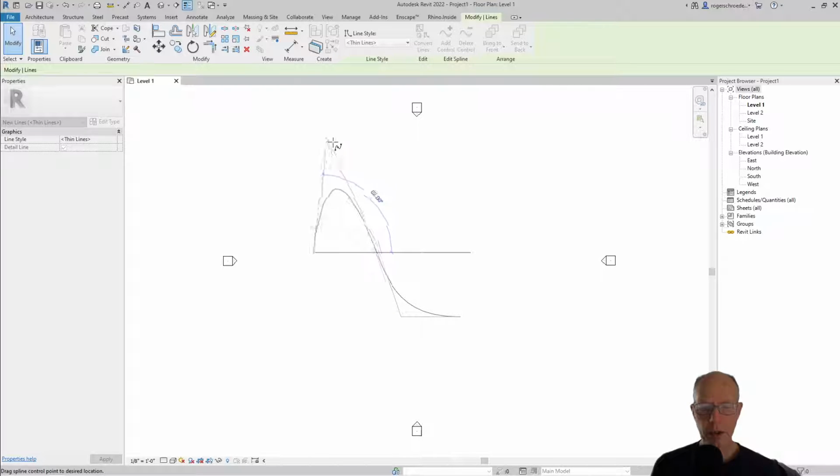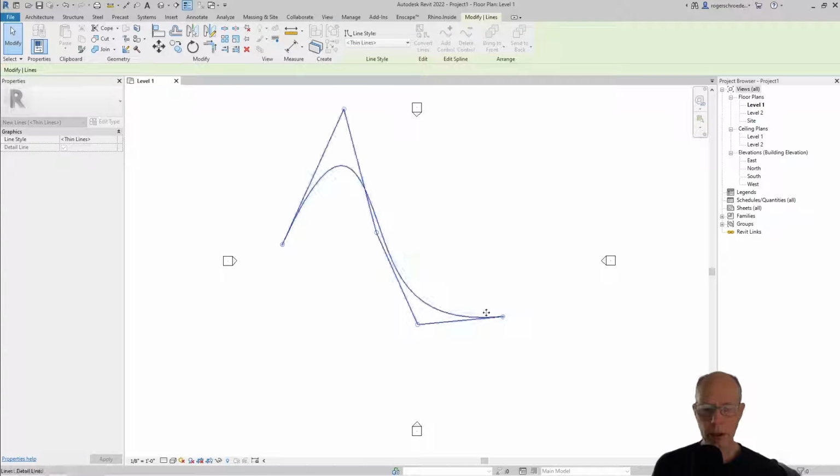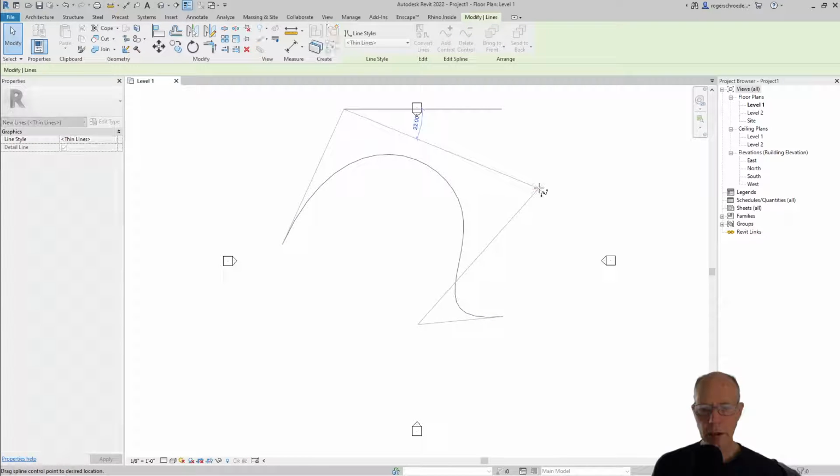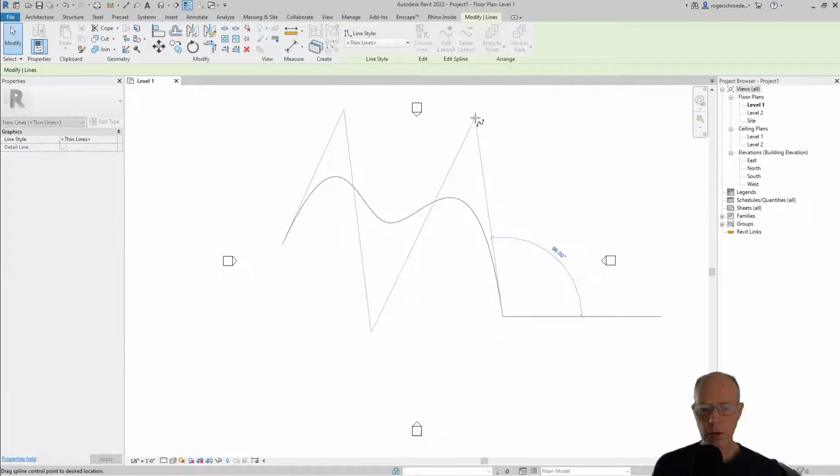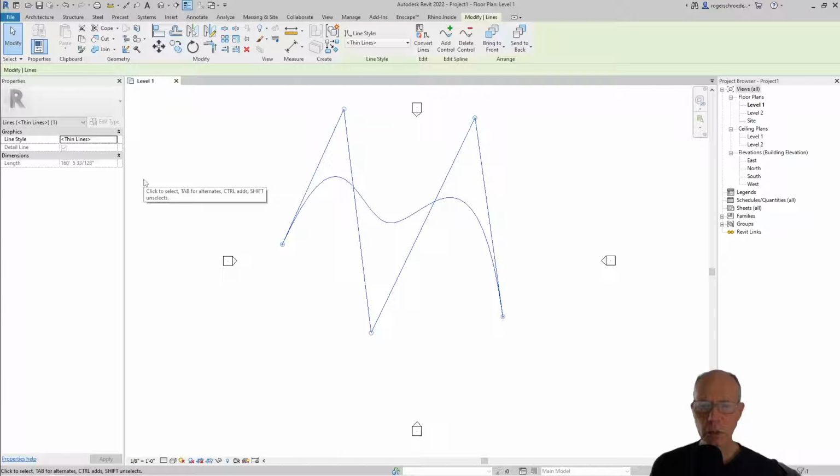So we can modify our shapes in many different ways. We have an end point and a start point, and then we have all of these to manipulate the shape of the curve. So we get tremendous amounts of control over how we shape it. It takes a while to develop a technique in order to modify these as much as possible. The caution I would give you is that less points are more. If you try to be very accurate by placing points to define a shape, it'll be very difficult to manipulate and correct that shape going forward.